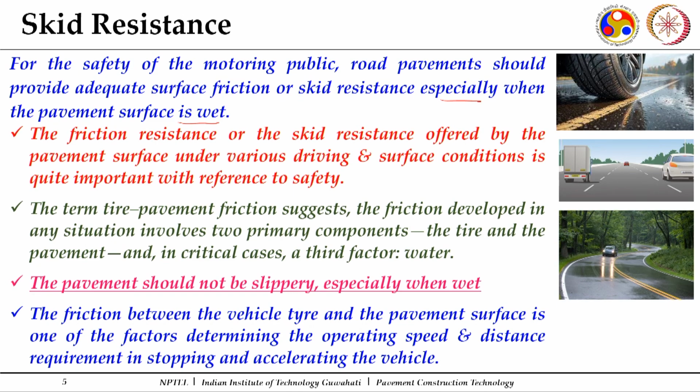Skid resistance and friction resistance play an important role for the safe maneuvering of vehicles over the surface, and this becomes more important when the surface is under wet condition. The skid resistance offered by the pavement surface varies under various driving and surface conditions. Driving conditions specifically refers to various speeds at which the vehicles are travelling. So, that also plays a role in the friction resistance of the surface.